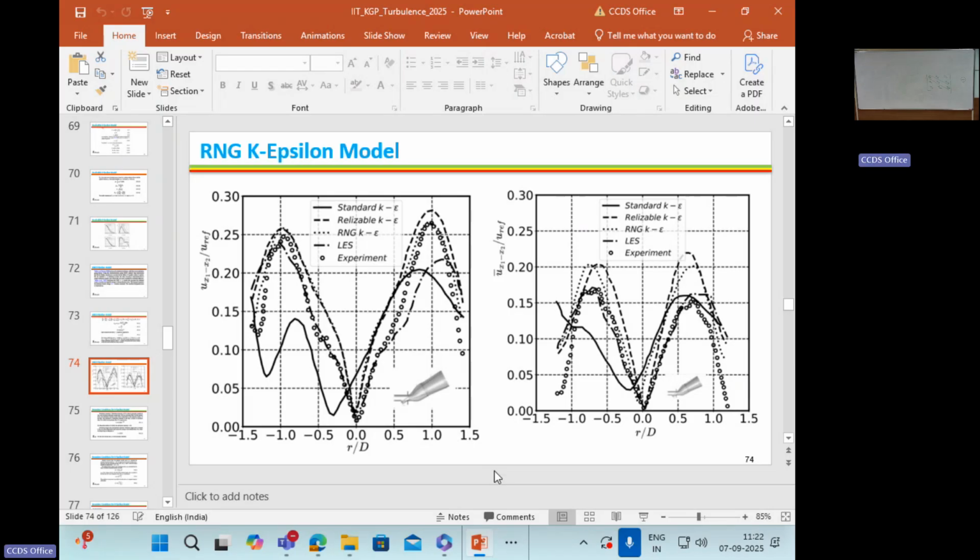Then mass flow inlet boundary condition, right? If there is a pipe, a certain amount of mass is coming. We have the mass flow inlet boundary condition, right? Similarly, we have some outlet boundary condition, pressure outlet, outflow, right? So now there may be a solid boundary where the no slip and no penetration conditions are satisfied, or there may be an inlet or pressure outlet boundary condition, right? At each boundary, we need to define the boundary condition for K and epsilon apart from the velocity, right? So now come to the boundary condition details, okay?